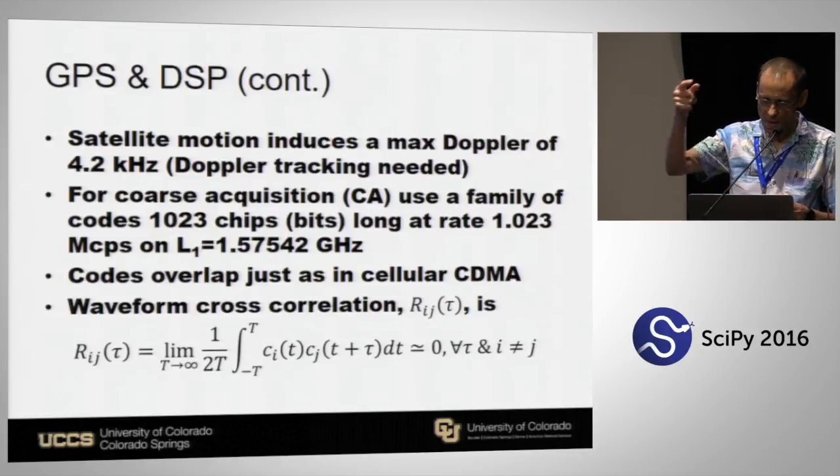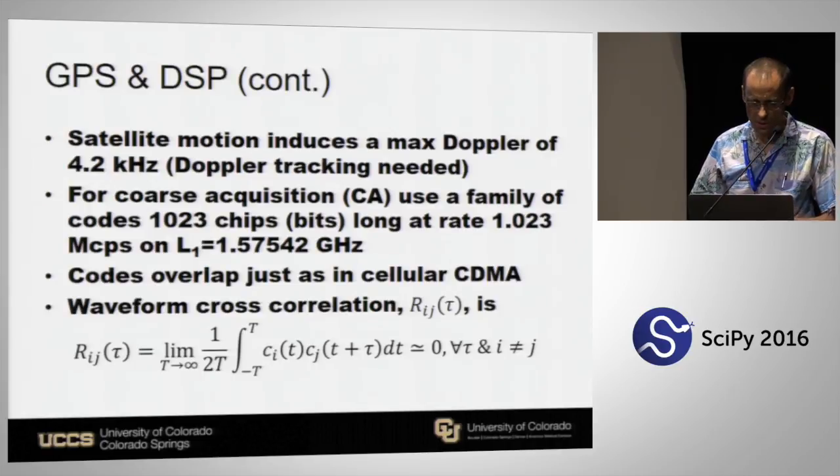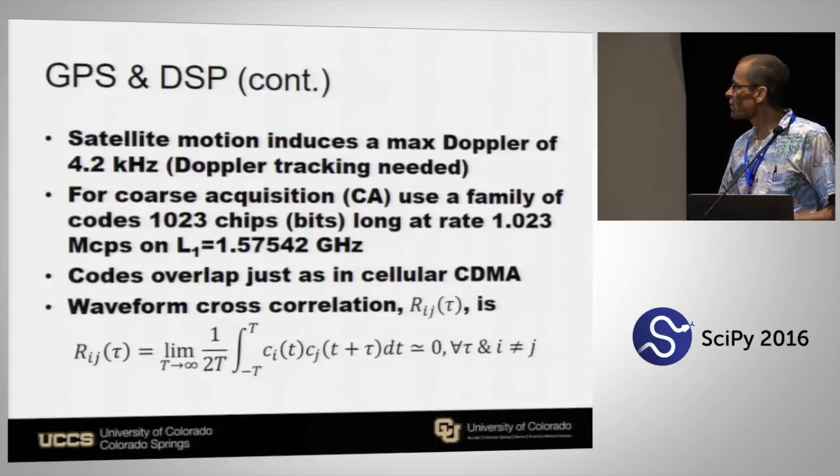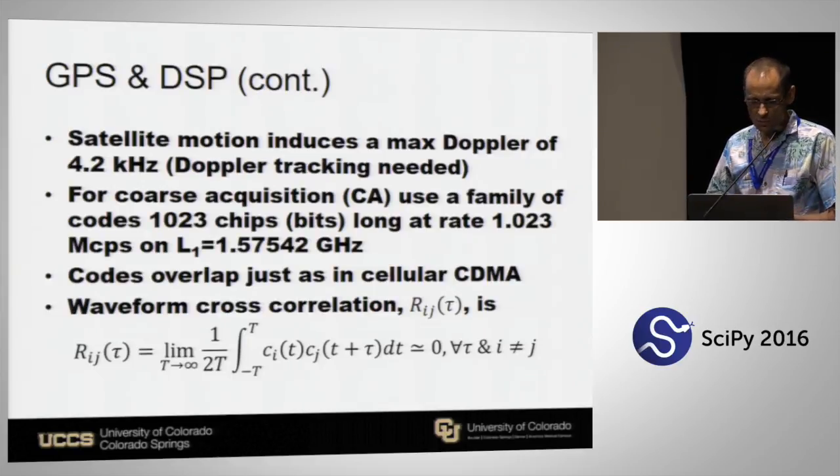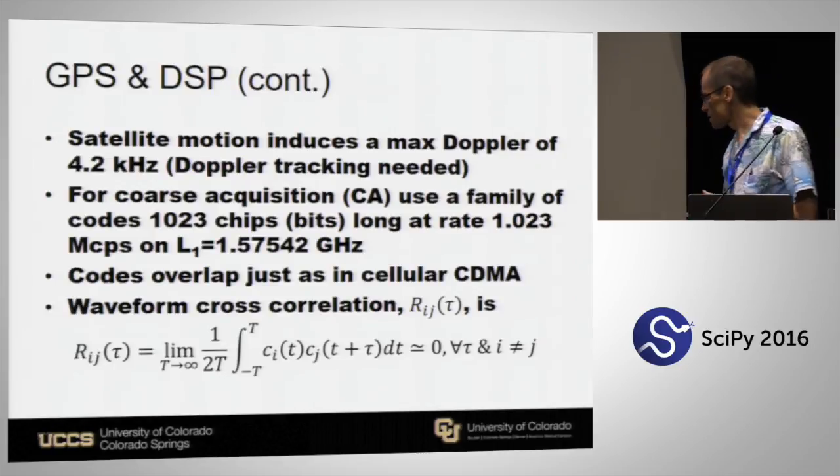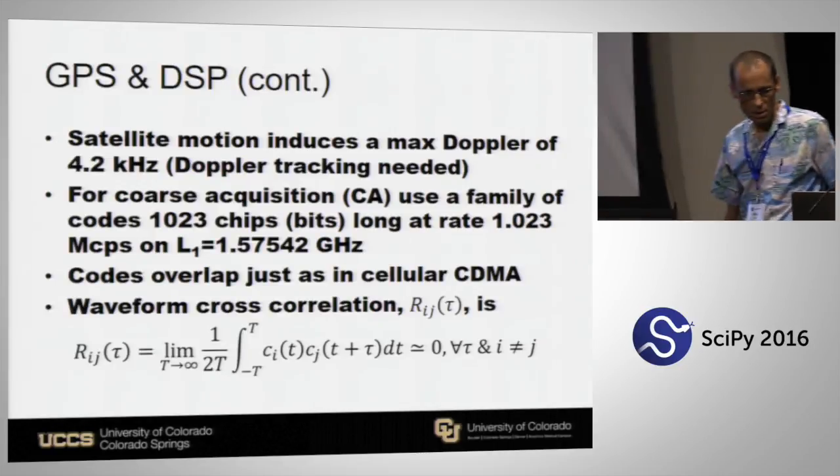So the radio that I'm passing around can tune to that frequency with software, and there's a Python module that somebody wrote that's available that allows you to do captures, so I can tune the RTL-SDR to that and do a capture. But then the fact that I have these CA codes from the family of gold codes is making them have an orthogonality property, and that's the next bullet here.